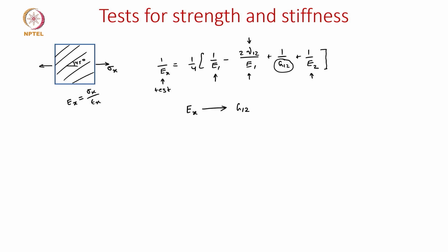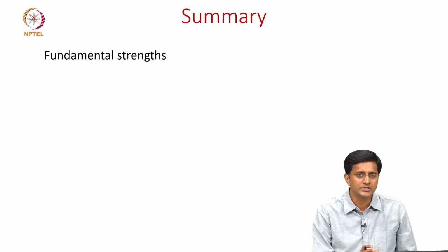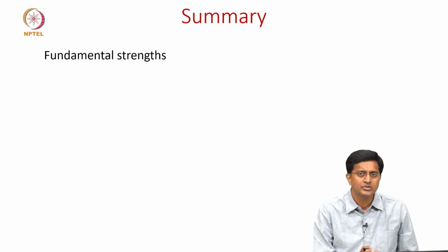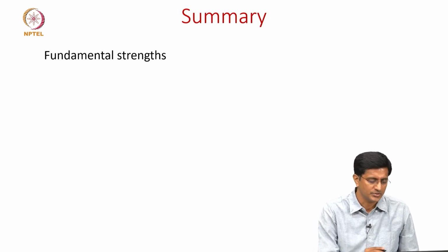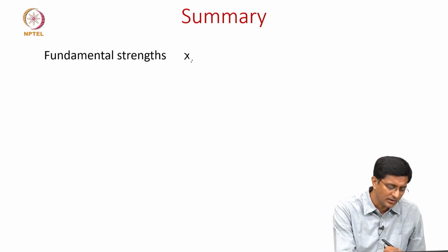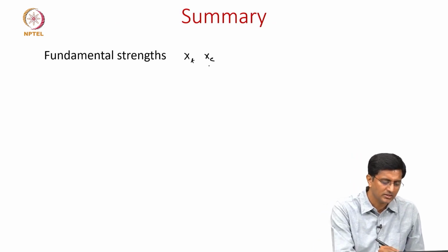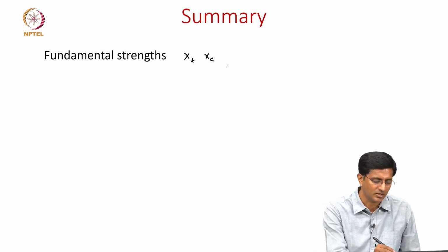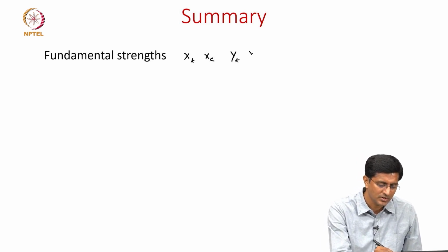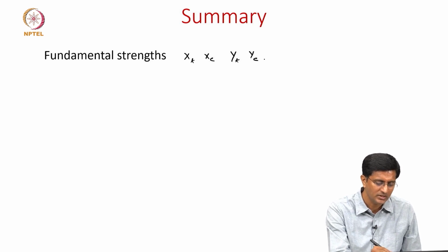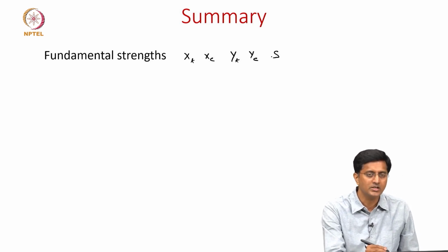So let's summarize what we have discussed in this video. We introduced some fundamental strengths for composites, namely XT and XC. These are the axial strengths in tension and compression. Similarly, the transverse strengths in tension and compression are YT and YC. And S is the shear strength.